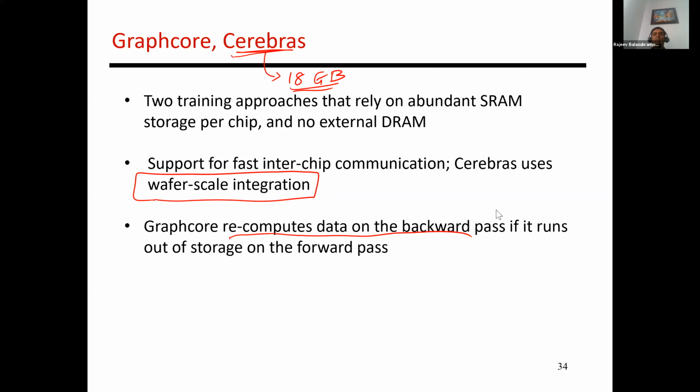Another related question is about using bfloat16 in the TPU, but using FP32 accumulation. So I did not know that they may be using more bits for the accumulator, and it certainly seems plausible, at least in inference, right? When we talk about the operations being done in 8 bits, the accumulator still uses 24 bits and then finally truncates the result to 8 bits, right? So this is done even in inference.